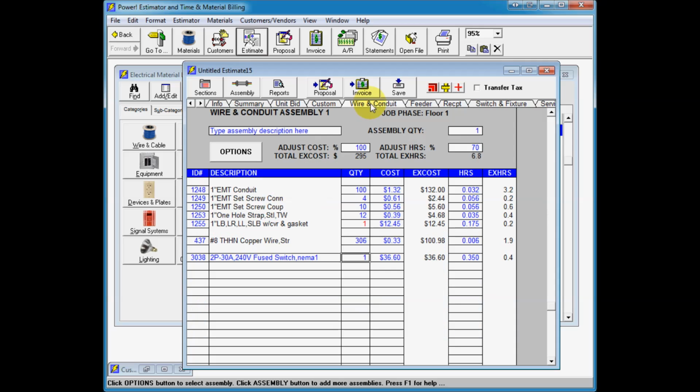Now let's talk about something that's very important: degree of difficulty, labor hour units. Remember, labor hour units are a decimal portion of an hour, a suggestion of how long it will take. But degree of difficulty is very important for labor units to be accurate.